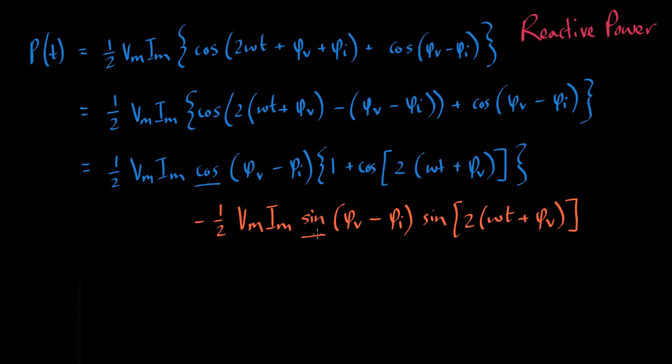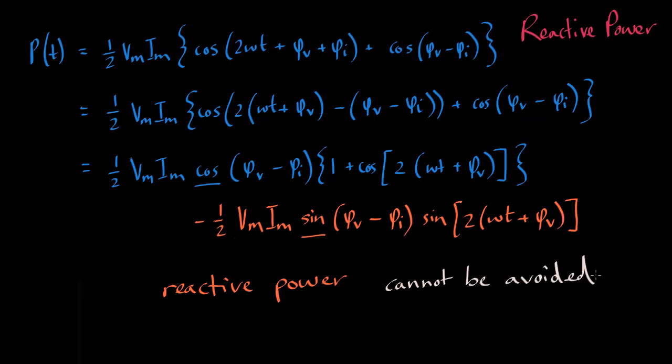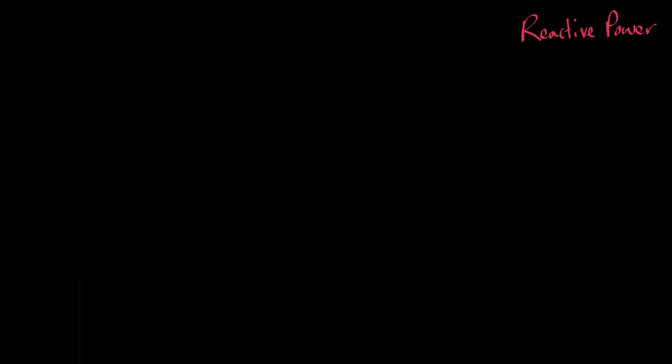This power flow represents the reactive power Q, and it is a continuous transfer of stored energy between the inductive and capacitive elements of the grid, with capacitors generating and inductors consuming reactive power. This does no useful work, but cannot be avoided. Reactive power is the power that magnetic equipment, such as transformers and motors, need to produce the magnetizing flux by which they operate. The expression for reactive power is given by